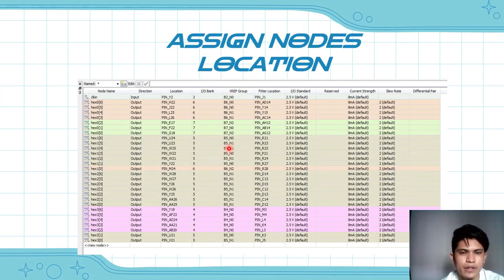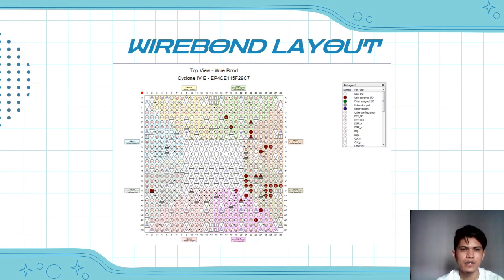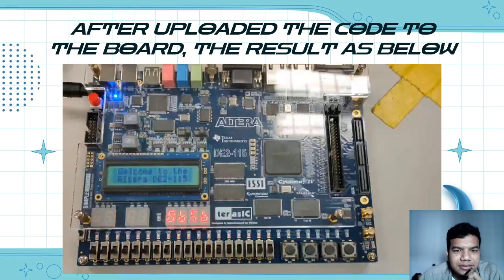Before we upload the Count0099 coding into the board, we need to assign locations to these nodes, and we got the locations from the user manual given in the lab. Then this figure shows the pin layout after we finish assigning locations to each of the nodes given. Okay, this is the result of 100 Hz.